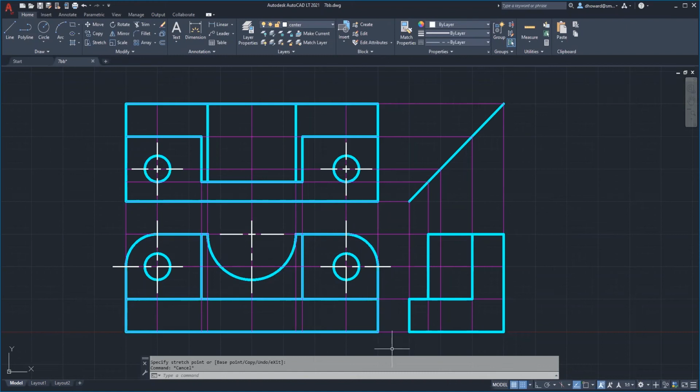Okay, so that is really all the head-on center lines. All the center lines that we have remaining are those for objects in their hidden view, or side view, including that same arc. So we'll just run a center line across it. There we go. So that is showing its center in the top view or its side view. And we'll do the same for these.